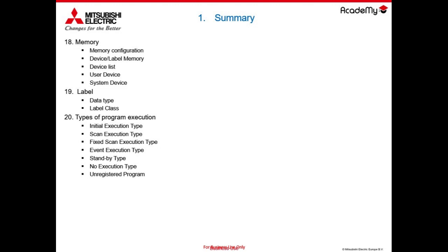When we talk about labels, we will differentiate local labels, therefore locally defined in a program container and therefore usable only from the same, and global labels, therefore globally defined in the project, which will be visible and usable from all the programs present in the project. We will also talk about module labels, therefore labels associated with smart modules.